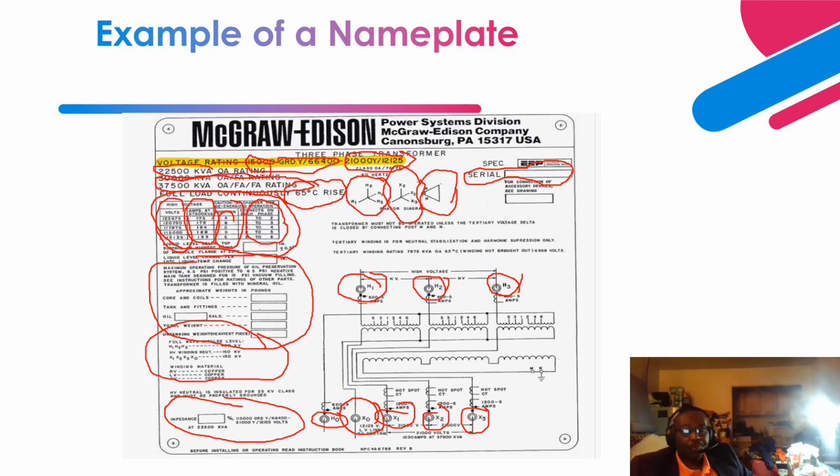Okay, so the low voltage side winding has basically two CTs, right? The first CT is 1200:5 in each phase. And to be able to determine the winding temperature of the transformer, a typical CT is utilized. So this CT is called a hotspot CT. Basically, it is used to measure the hotspot temperature.